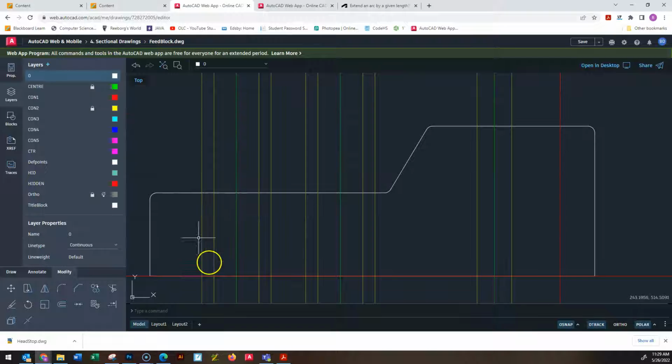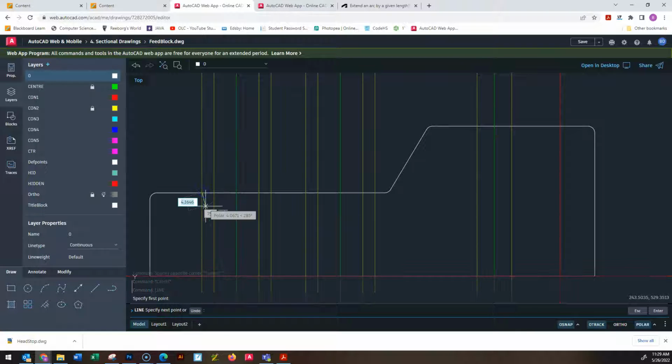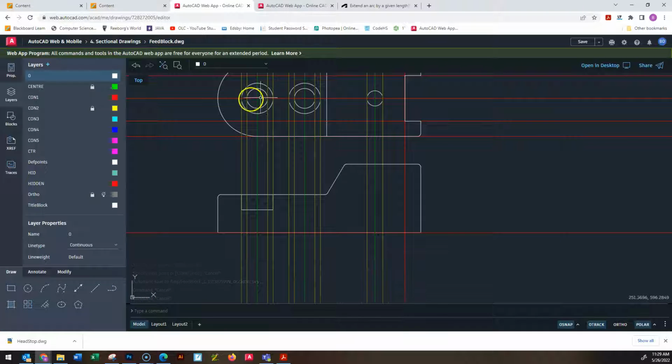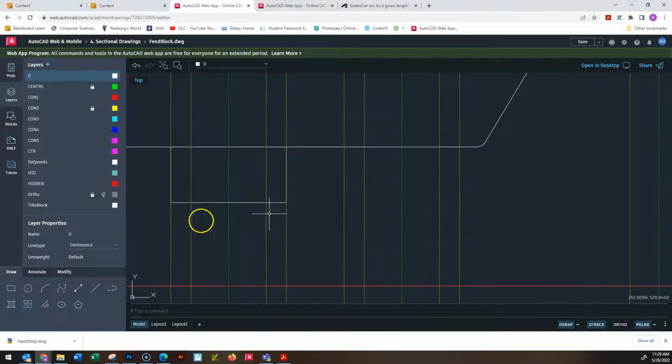And because we don't have a second depth, we know that it goes right to the bottom of the object. So I go right to my object line tool, and this is the very outside. I know it goes down 10. I know it goes all the way across to the far side, and then I know it goes up to the top again. So I just took the outside lines, and now I need to move to the inside lines.